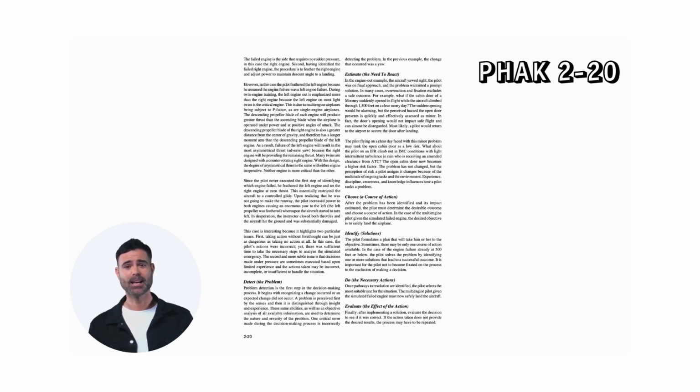Second, having identified the failed right engine, the procedure is to feather the right engine and adjust power to maintain descent angle to a landing. However, in this case, the pilot feathered the left engine because he assumed the engine failure was a left engine failure.